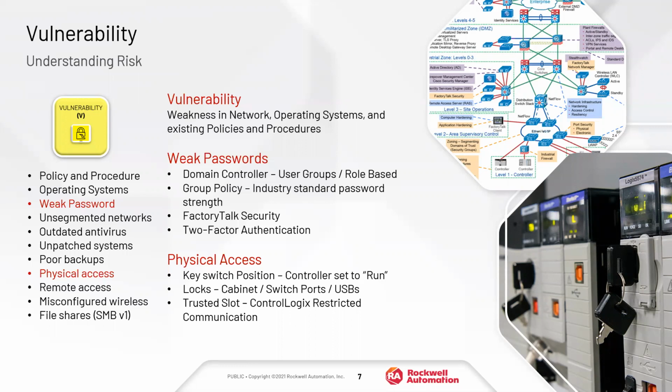So when we look at countermeasures for this, implementation of industry standard password management, there's a lot of documentation around that, specifically around Rockwell. So one quick example is removing all user access when we start talking about FactoryTalk View on the HMI side, the SCADA side, the DCS, making sure that there's no global automatic access into the system. It all should be dedicated to a user or a role.